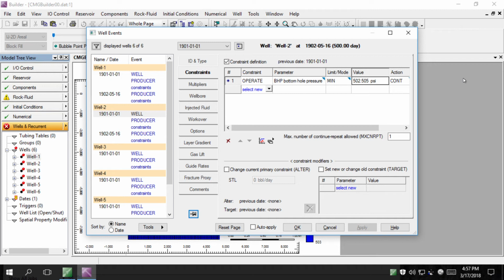For the conversion of well number 5 and 6, we're gonna do a different procedure. CMG doesn't allow us to change a producing well to an injector well, so we're gonna trick it by shutting off the current well and starting the injection from a new well.